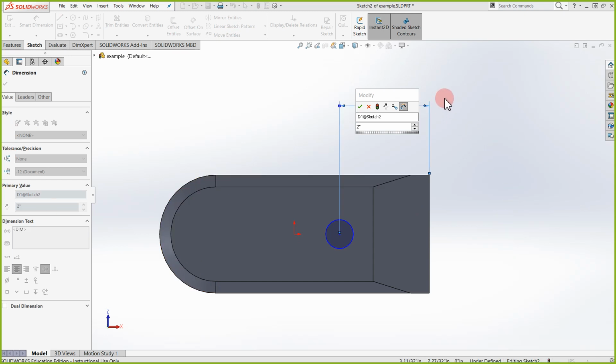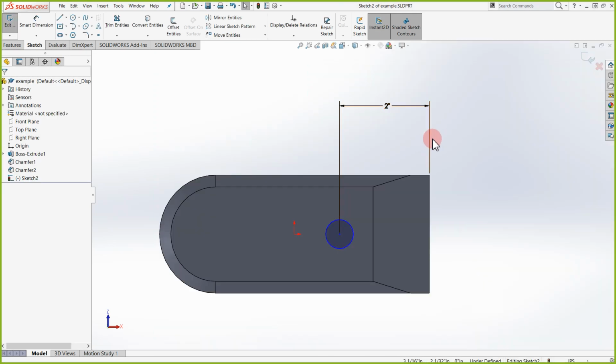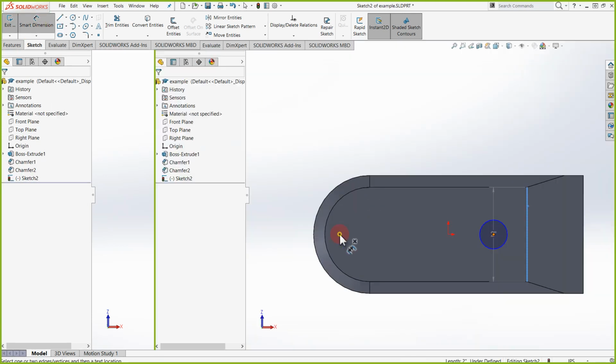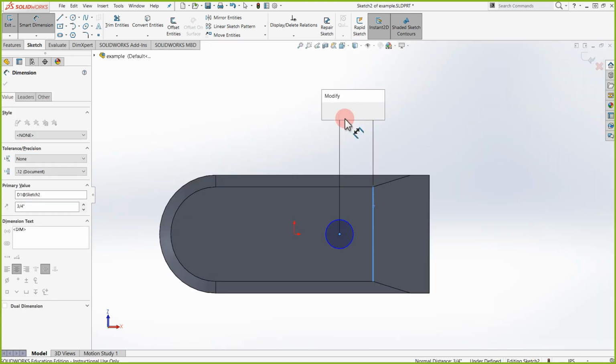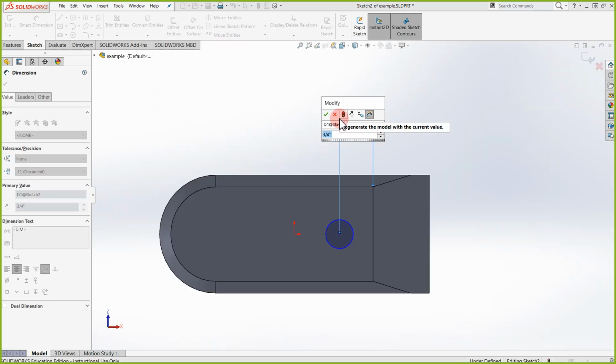So because of the glitch, like I said, if you see it glitching, save and restart your SolidWorks. Now I have my dimensions back. So let's just find what the dimension was quickly so I can finish this one. From the first edge, which is this one over here, we see that it is not from there. This dimension should be from Smart Dimension, from here to here. From this edge here, our first dimension is, let's see, 1 inch.